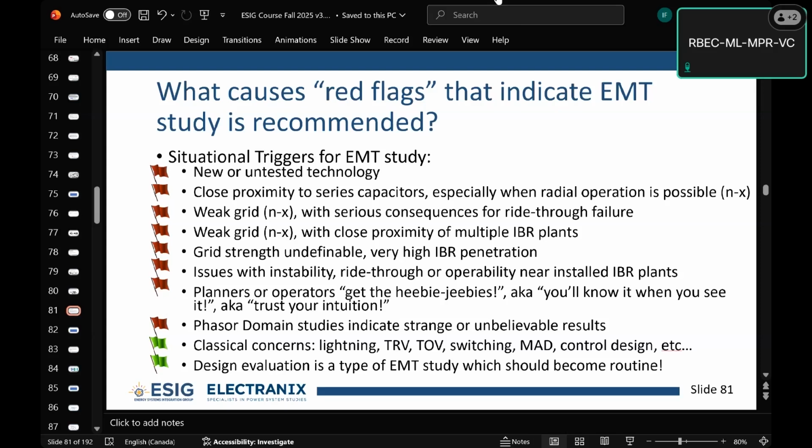There's no short answer to your question, I think, except for sensitivity studies, experience, and also not sweating the details too much with EMT. You can do a lot of sensitivity studies that show you, yeah, you can add all that detail and it'll change the result by just a really small amount. So let's not do that. Let's focus on the things that can really change the result, like the code and the inverter model, for example, and bring the study as close as you can to a useful thing in a short amount of time.